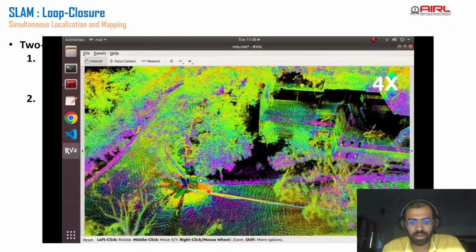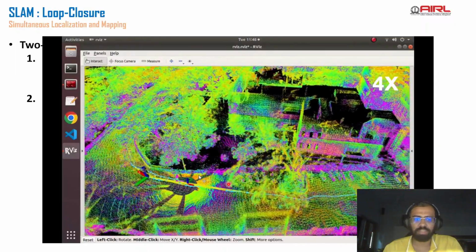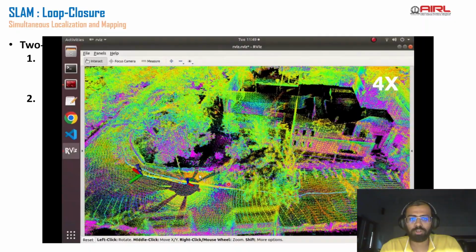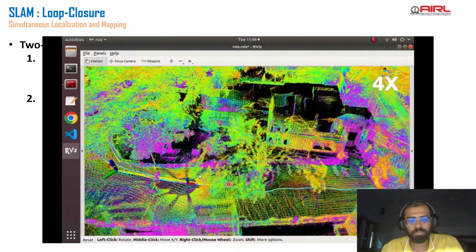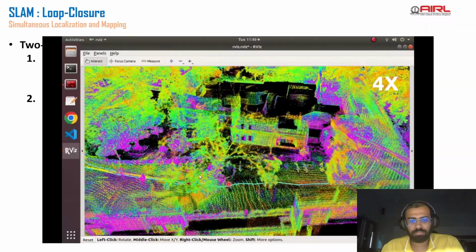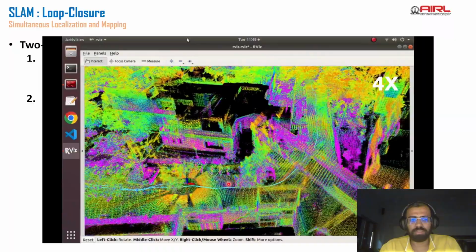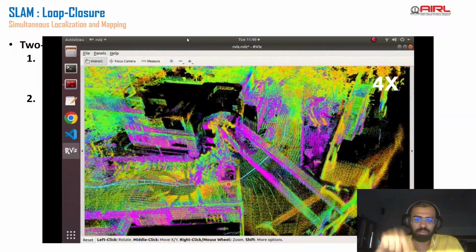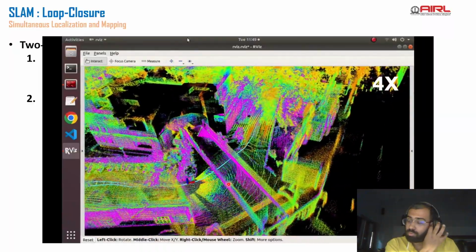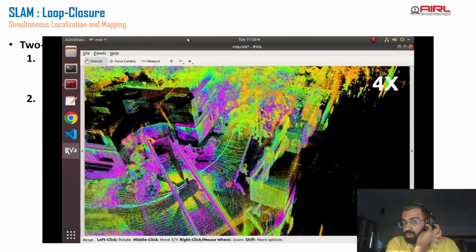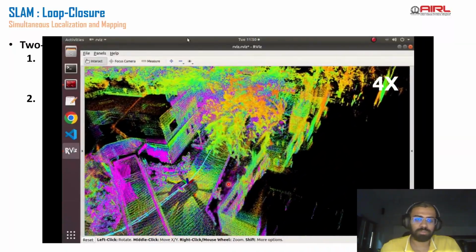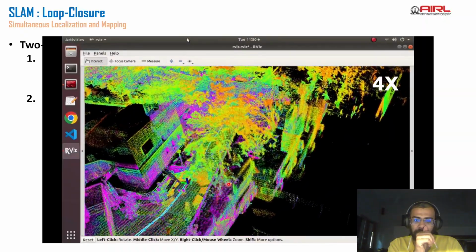This is where we started, and now you can see a lot of yellow lines come into play because a lot of loop closure factors would happen. Blue is my current odometry, and the interlinking lines between two blue lines are my loop closure factor indicators, basically.